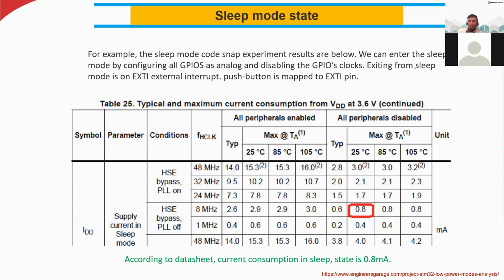And exiting from sleeping mode is done by an EXTI, external interrupt. The push button is mapped to the EXTI pin. So we are giving this signal, the interrupt signal, externally. Then immediately the microcontroller will resume back. It will come back to the active mode.